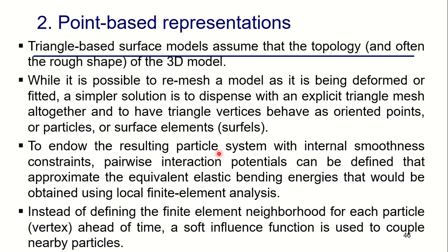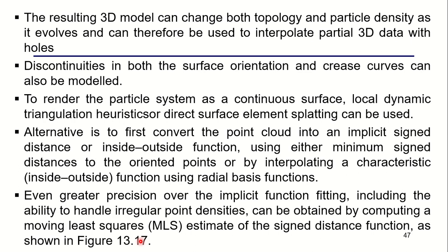To endow the resulting particle system with internal smoothness constraints, pairwise interaction potentials can be defined that approximate the equivalent elastic bending energies that would be obtained using local finite element analysis. Instead of defining the finite element neighborhood for each particle vertex ahead of time, a soft influence function is used to couple the nearby particles.